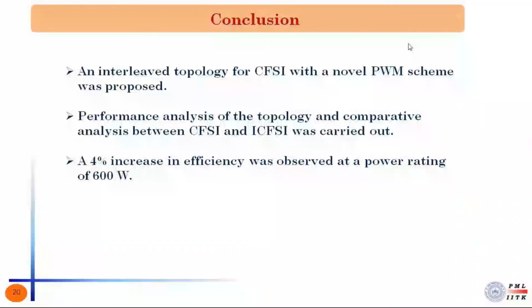Now here I'm going to conclude. So in this webinar, we saw an interleaved topology for CFSI with a novel PWM scheme, and also we did the performance analysis of the topology in comparison with the current fed switched inverter, and we saw a significant improvement in efficiency as a result of interleaving. Also, we achieved improved gain characteristics as a result of interleaving, and we saw 4% increase in efficiency at 600 watt. Thank you.